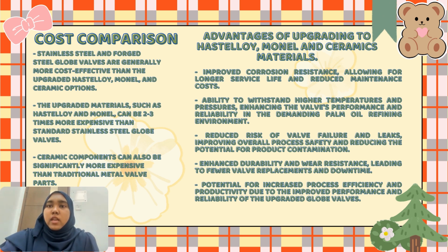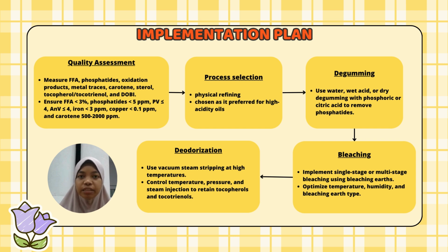globe valve. As the conclusion, the choice between the current and upgraded materials for globe valves in pump or refining processes will depend on factors such as the specific operating conditions, the aggressiveness of the media, the required temperature and pressure ratings, and the overall budget and cost consideration. While the upgraded materials offer superior performance, the increased cost may not always justify the investment, especially in less demanding applications. So next, I will explain a little bit about the implementation plan of the refining process of cooking oil